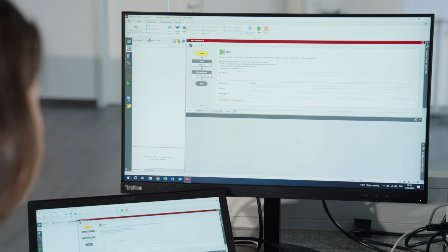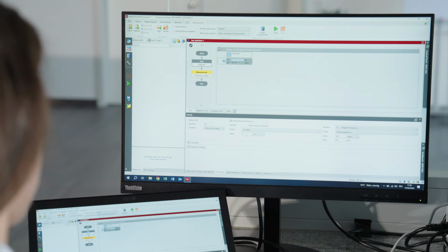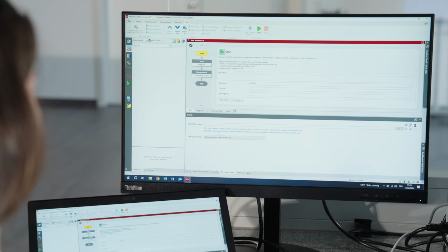In the software, open the template Frequency Sweep, type in the shear strain value depending on the sample type, set the angular frequency range, for example from 100 rad per second to 0.1 rad per second, and start. So, understanding and accurately measuring the various rheological properties of battery slurries is very important during this crucial step in the process of battery manufacturing.